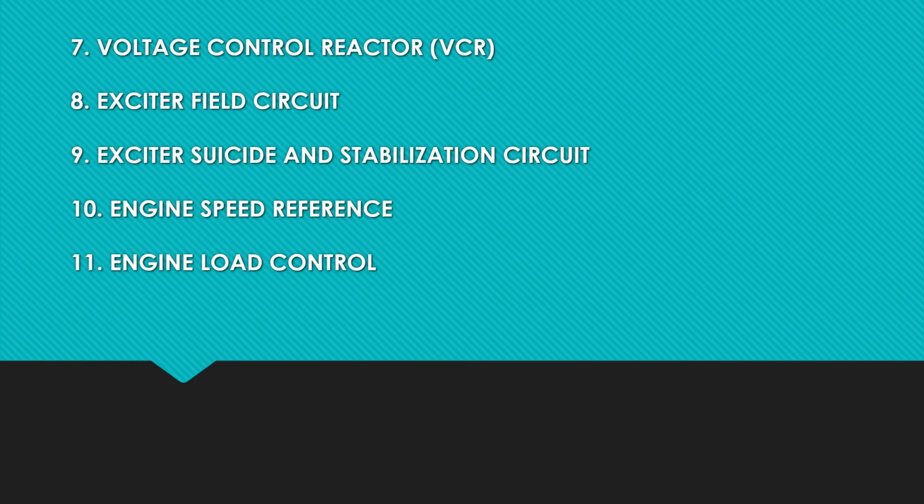The exciter field is fed from the locomotive battery through a network of resistors EFR1, EFR2, EFR3 and EFR4 and the transistor EFT. The power transistor EFT is turned on and off 800 times per second as explained before. With EFT turned on, current flows through exciter field via EFR1, EFR4 and EFT. When EFT is off, a negative current is permitted to flow through exciter field via diode XD23 and EFR4. This helps to reduce rapidly the exciter voltage.